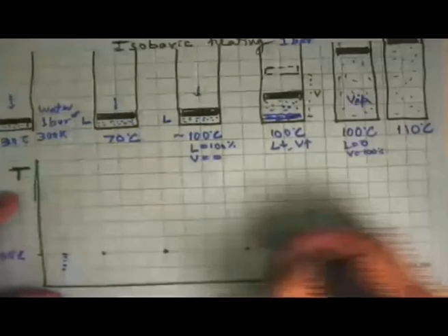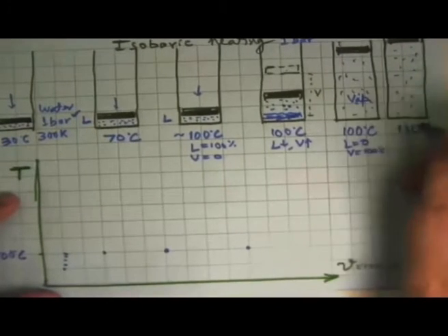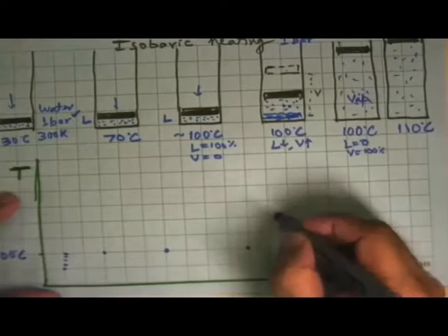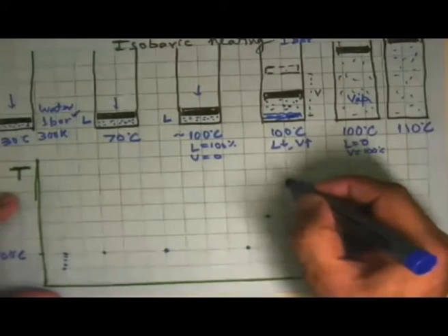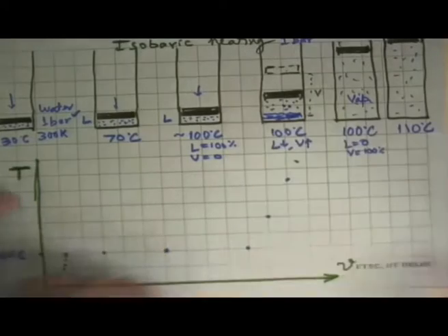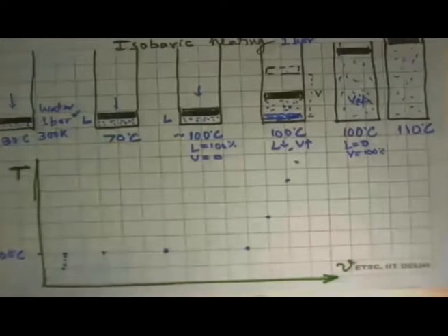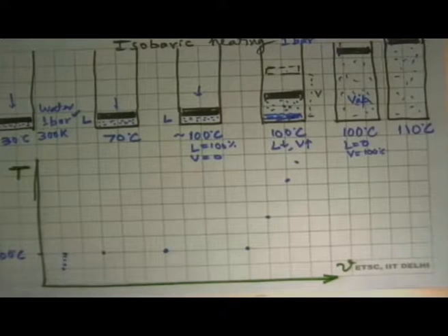So this point would then show that temperature has increased, volume has also increased, so it will go this way, and we can get a point there. And if you continue heating, these points will keep going. This is some example I have taken of water, but one can do the same thing with practically any substance. You can say take nitrogen at 77 Kelvin, or say nitrogen at 1 bar pressure starting from 70 Kelvin, it will do the same thing. Take butane, take a particular pressure and start from say 10 degrees Celsius and start heating it, it will do the same thing. So all substances under certain pressure and temperature conditions will have this behavior.